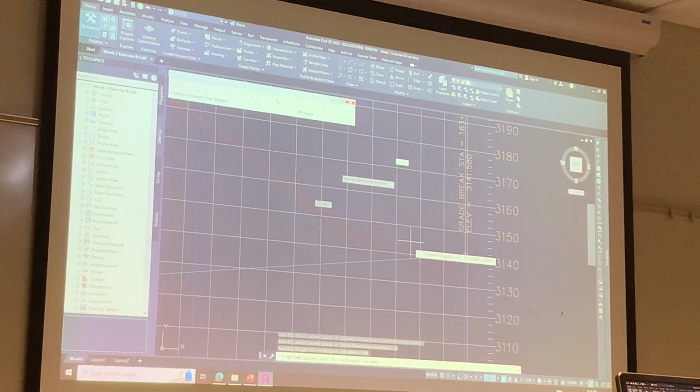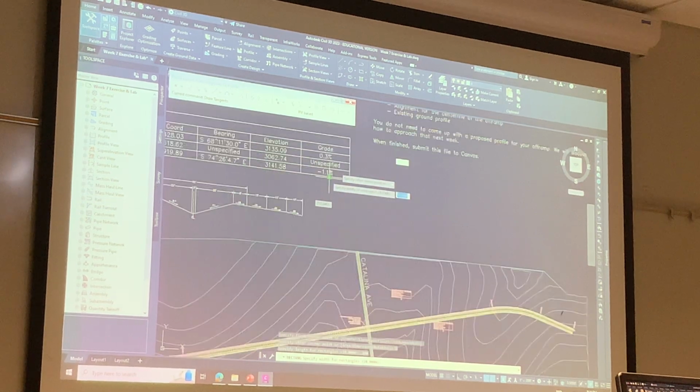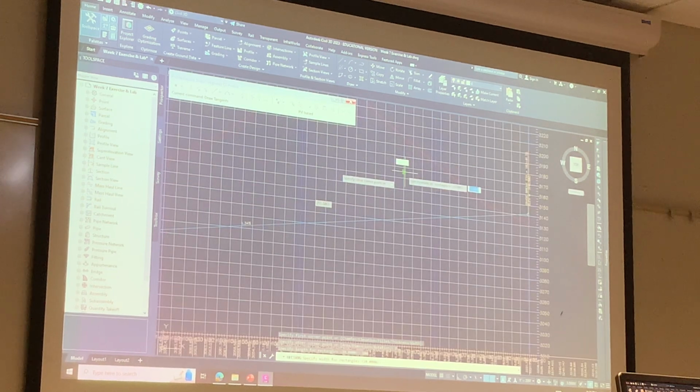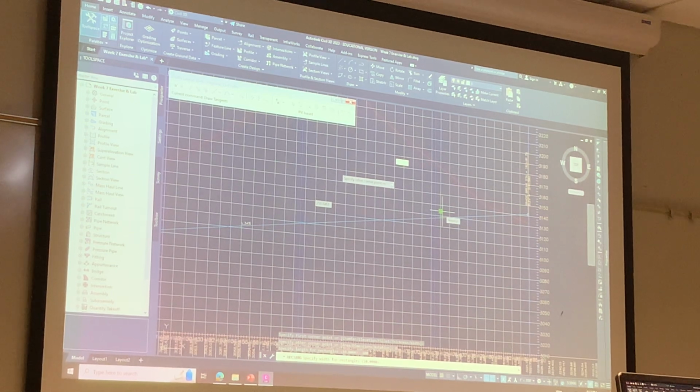Click enter. What is my vertical distance going to be if I need to go up at a 1.1% slope? It's 100 feet over and up. I'm going to say 11, because one point something times 10, and I was struggling with that last time. Yes.